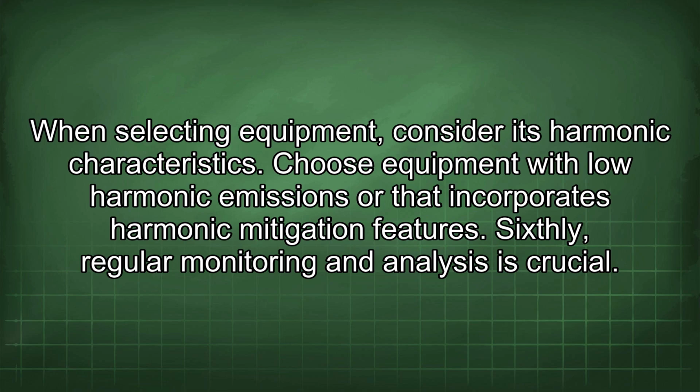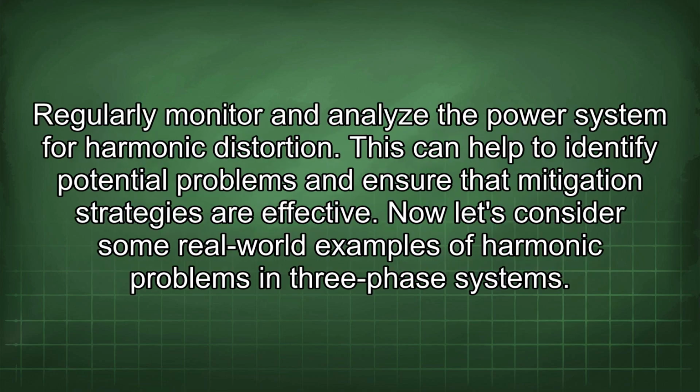Sixthly, regular monitoring and analysis is crucial. Regularly monitor and analyze the power system for harmonic distortion. This can help to identify potential problems and ensure that mitigation strategies are effective.